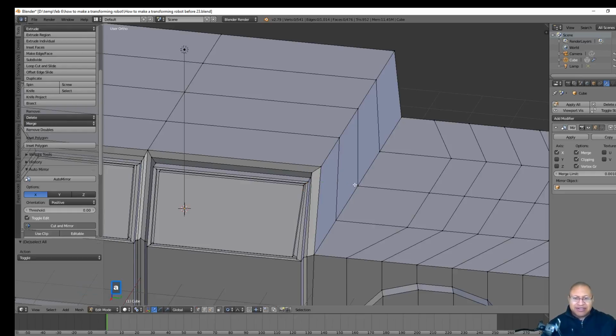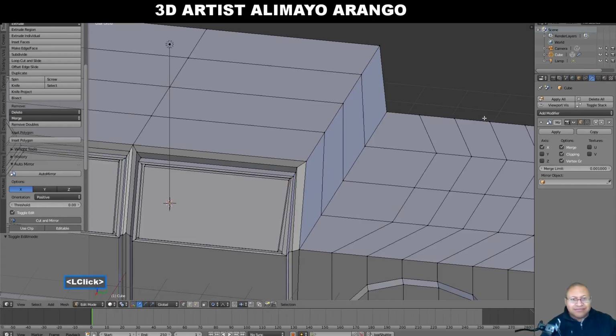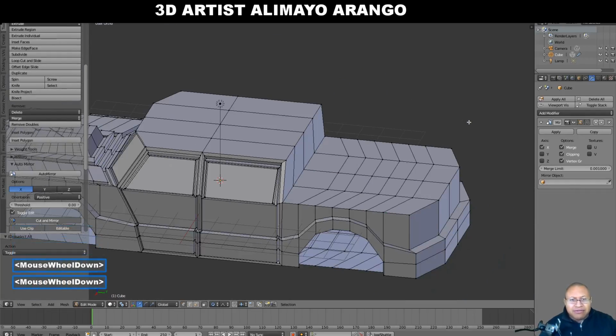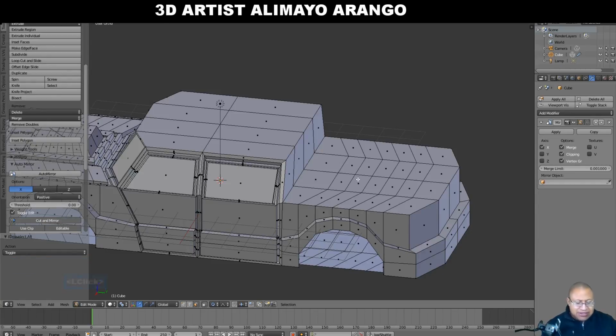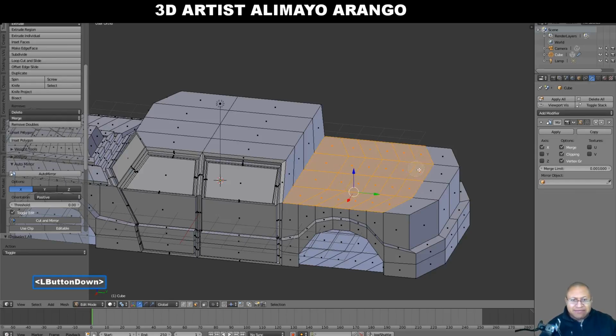Now we'll press A to deselect. Okay, we're going to roll the middle mouse button to zoom back. We're going to get to face select. I'm going to press the O key to go back to regular proportional editing, and then I'm going to press O again to turn off proportional editing. I'm going to press C for paint select. When I first came in to this particular video segment, as I was deselecting, when I start the recording, typically I have to click on the screen to have it activate, so I click the vertex by accident.